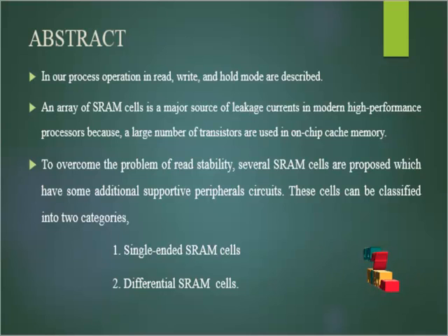In the proposed design, we are using the differential structure because the sense margin is improved. It shows larger read current, shorter read delay and better read stability. The low power 8T cell is robust to process parameter and voltage variations. Our 8T SRAM cell also has a higher read current to leakage current ratio, and the leakage power consumption is also less.